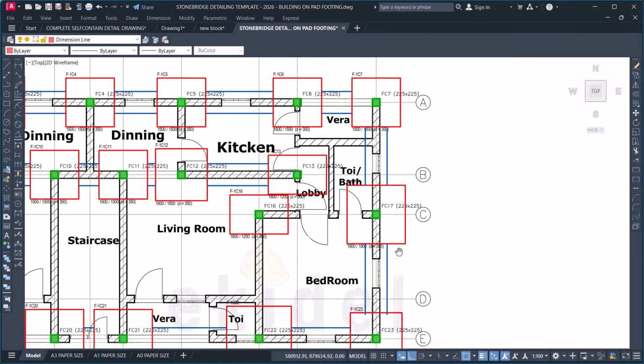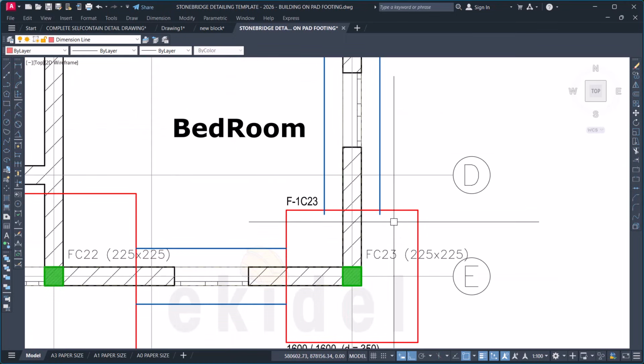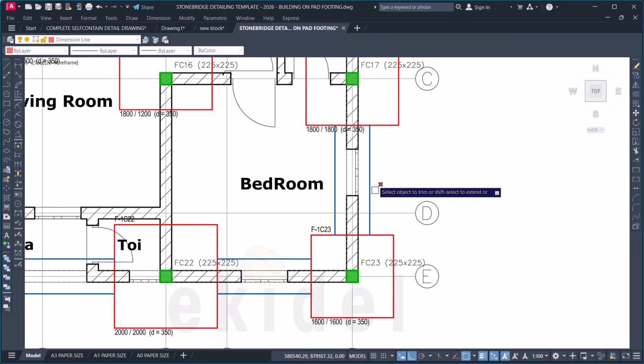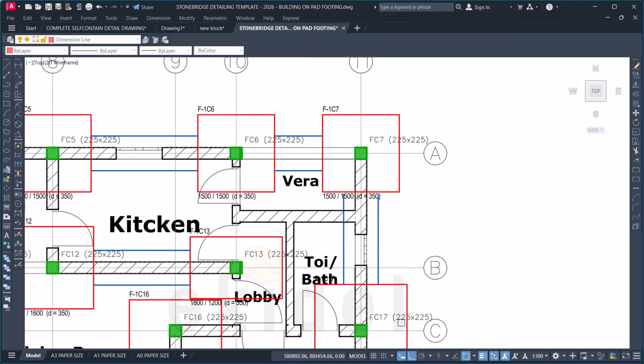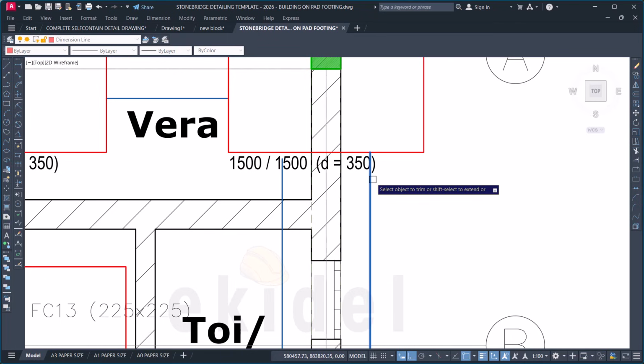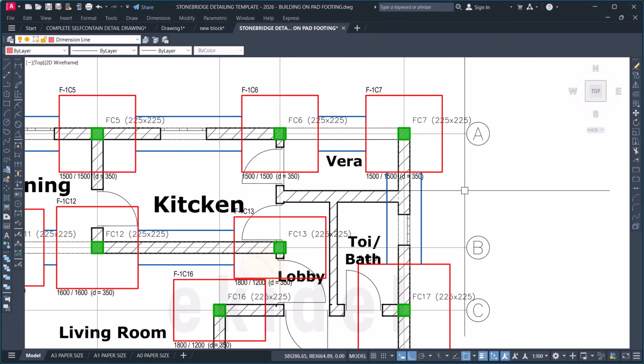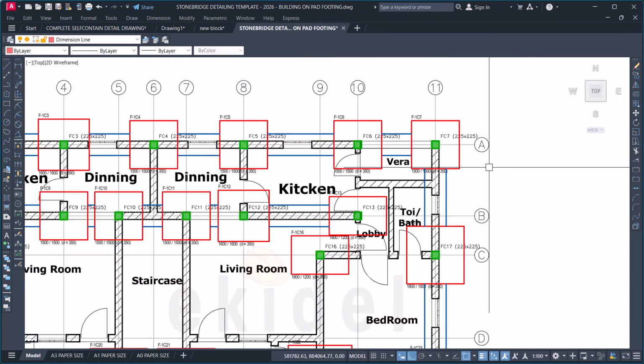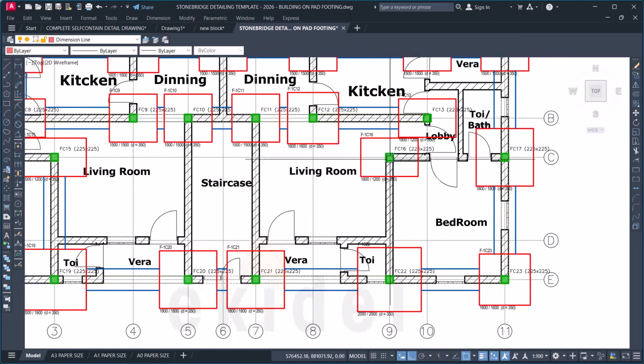Okay, so with this now we now have this here. I can choose to also trim off this. You can see the excessive line here, trim, and then check here is okay, and then here you can see, hold my shift key, extend. So whenever you are doing your trimming, if you hold the shift key on your keyboard, that is extend, the opposite of that.